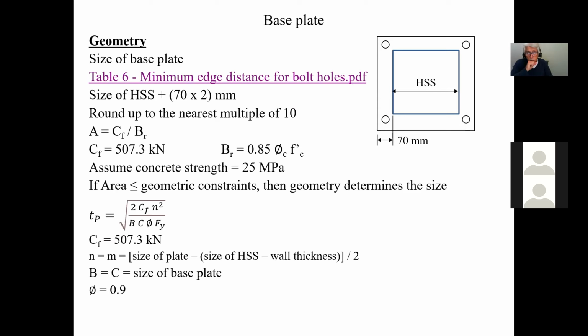Now, excuse me. So now you're able to size the column, you're able to size the base plate, and on top of that, you'll be able to specify the columns on your drawing and do the detail of your base plate. And when you do the detail of the base plate, don't forget what you're going to be doing is this. You're going to be drawing this to size.